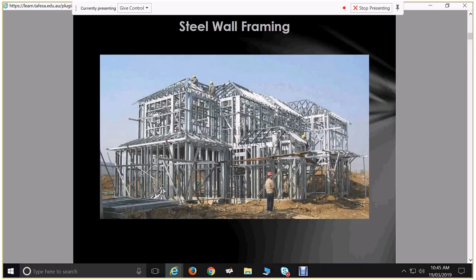And they're typically now calculated as essentially being trusses as well. So we can see this little opening here. We've got a large window happening there. We've got this bit happening above. That is much like a lintel in your timber framing, and these are much like your jack studs, except that because of the way that these are fixed, that whole thing is working as one. So that's working like what is actually called a ladder truss. But you'll also see steel frames where you've got those jack studs on an angle that end up working like webs in a truss.